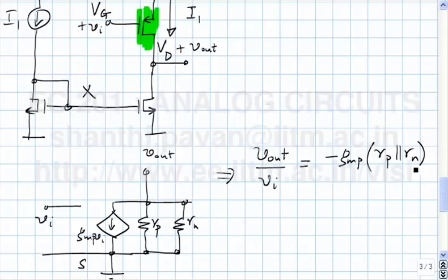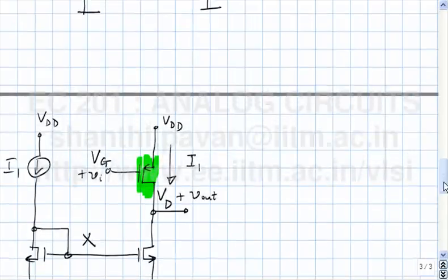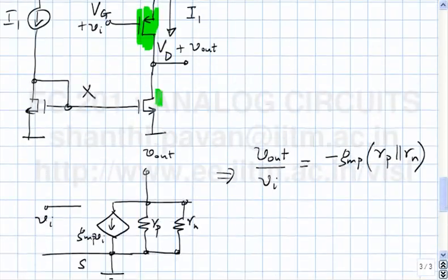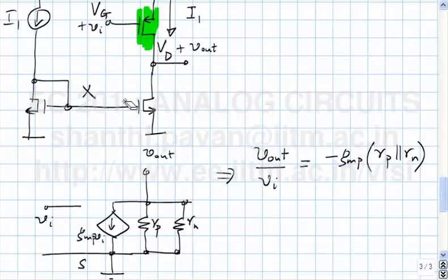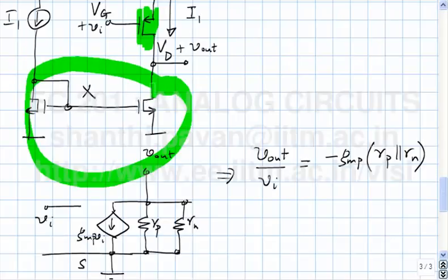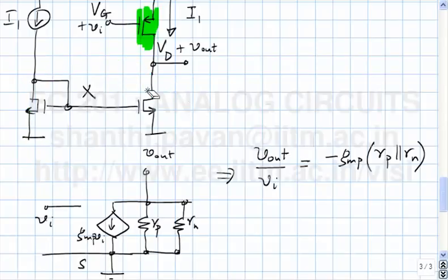Okay? And you can see that all the NMOS transistors are doing is presenting a load to the PMOS device. And you could have derived it another way. We went on saying that the incremental gain is minus GmR. So if you wanted an infinite incremental R, you could have put a current source. And that's precisely what this is. If the transistor is ideal, this is an ideal current source, and that will result in a very, very large gain.